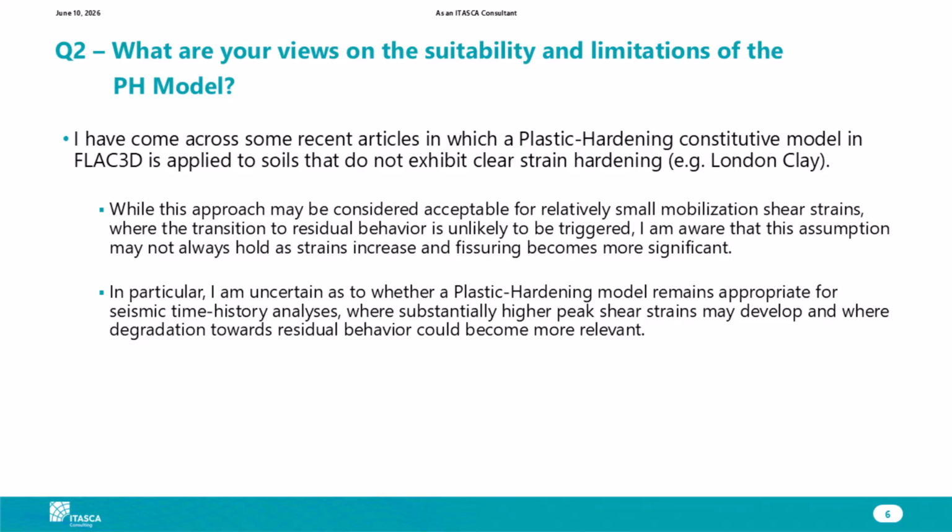Yeah, so I see that the time history could become more relevant. Yeah, the degradation. If you have a material like a hard clay that after 1% of strain degrades to 50% shear strength, then you might be in trouble. You can come up with some kind of trick, taking, I don't know, 50% or 75% of the shear strength, but essentially it could be a poor hack because the constitutive model is not designed to capture that type of behavior. But in static condition, as I showed earlier, it can be done, and you can also take the loading, unloading, and reverse, and go back to the original reduced strength.